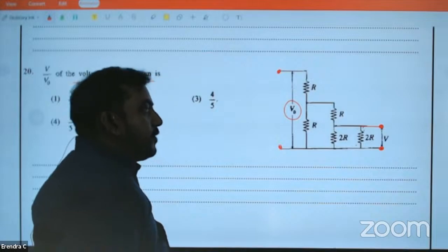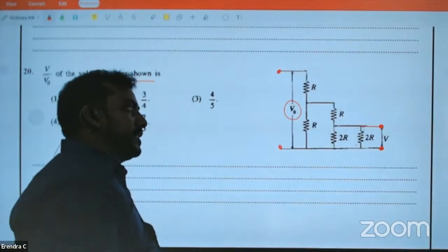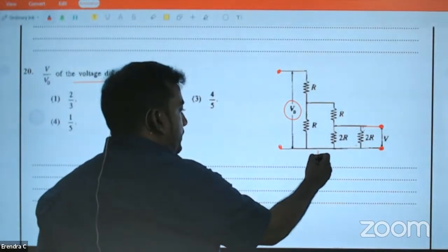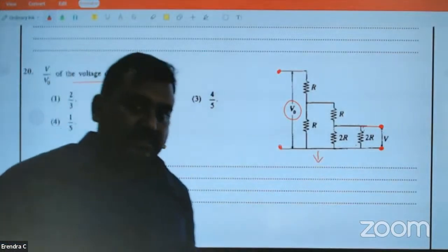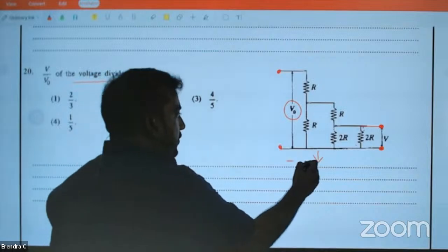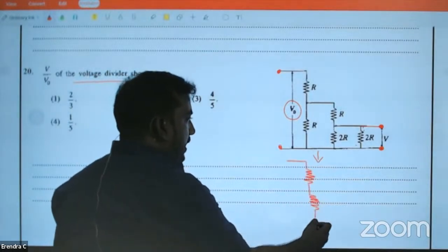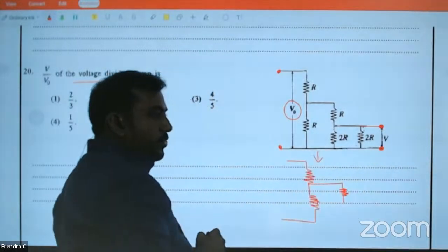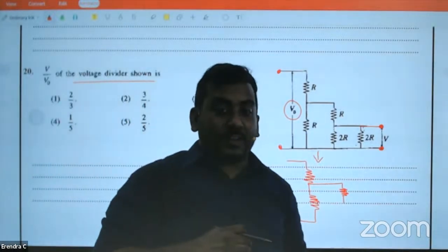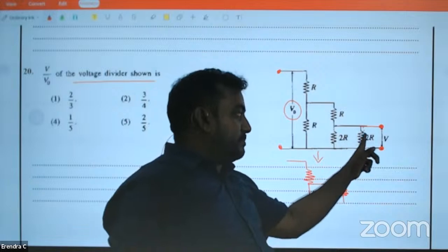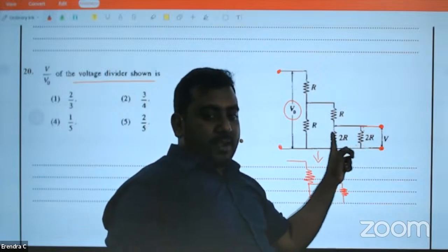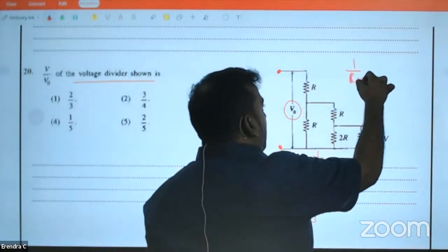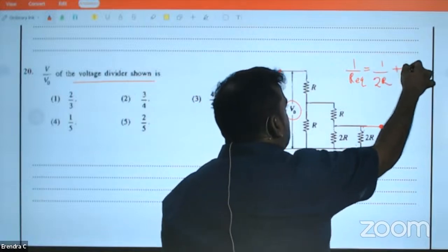Now, when you need to find the potential difference across this, these two resistors are parallel to each other. Parallel resistors have the same voltage, right? So if I draw this resistor R, here also resistor R. Parallel resistors, how do you find the equivalent? When we were doing capacitors also, I told this. Parallel means multiply both, divide by the addition. Or the O-level way, parallel means 1 over R equivalent. You will apply this and get the answer.